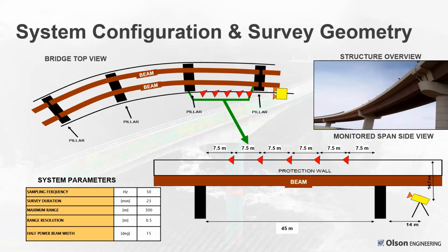As Larry mentioned, because this was a concrete girder bridge, fairly smooth underside, there's not a lot of natural reflection points. So what we needed to do was to add some nice reflectors. So we have these corner reflectors, we call them corner reflectors. They're aluminum, we had them manufactured, and it's kind of like a prism where the radar will shine up in that corner and then bounce back towards the radar unit.